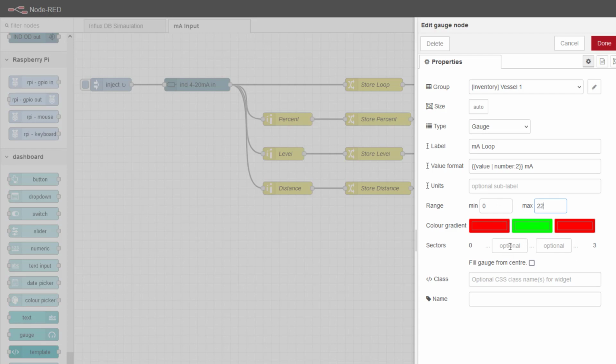Your operating range for your milliamp output is 4 to 20, but you can program fail-safe positions. So during normal operation, the milliamp loop will work between 4 and 20. When the device that's transmitting the 4 to 20 signal thinks it's in error and it's not happy, it will go to a fail-safe condition, and that's either fail-safe high or fail-safe low. So you can force it to go. Normally it's about 3.6 or 3.5. It'll be below 4, or it can be 22 milliamps.